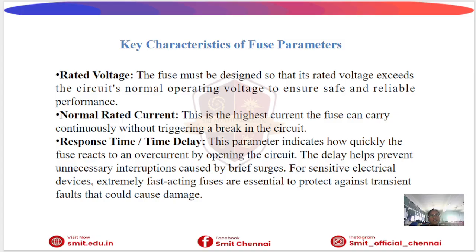Then key characteristics of fuse parameters. The important parameters of a fuse include rated voltage, rated current, and response time. Rated voltage: the voltage rating of the fuse should be higher than the normal operating voltage of the circuit. Rated current: the maximum current the fuse can carry continuously without melting. Response time: this indicates how quickly the fuse reacts to overcurrent. Fast acting fuses are used for sensitive electronic devices.